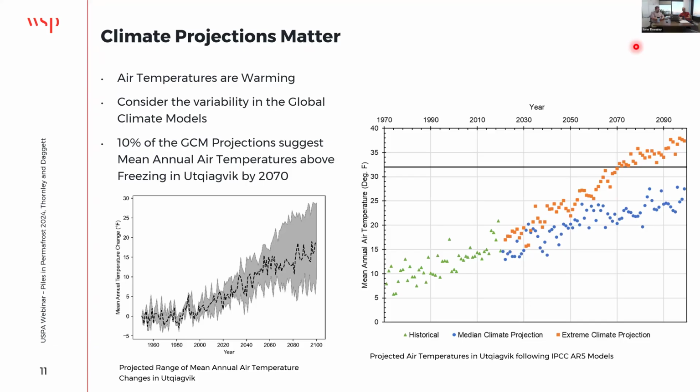If we're trying to design something for 50 years, what are we going to do? We cannot design something for today's temperature and expect it to work in 50 years. We're seeing that right now with things that were designed in 1980. We're currently retrofitting across the state to improve the foundation or change the performance of it and assess it again, because what they designed for in 1980 is no longer valid in 2023.